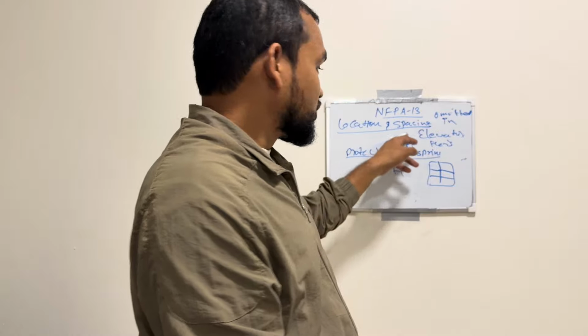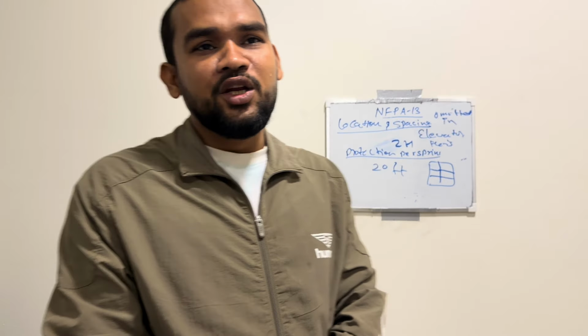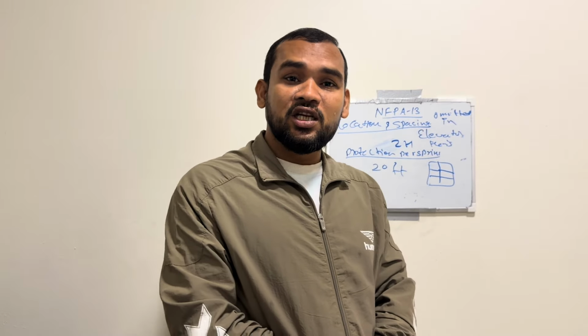Sprinkler spacing shall be measured and covered along with the ceiling. Distance from the wall shall be considered for the spacing from the sprinkler. A minimum distance between the sprinkler and deflector position and orientation shall be required. Orientation should be parallel to the ceiling roof, and any type of obstruction is not required. For obstruction less than or equal to 18 inch below the deflector, a special supplementary sprinkler shall be required in this case.